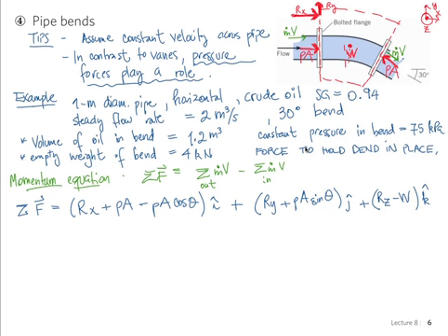Would it be wrong to put the second pressure force inside, along the momentum? Inside, like inside the control volume? Remember, we don't care about anything that happens inside the control volume. The inside of the control volume is a black box. That's the whole purpose of this type of analysis. We draw a black box. Everything that happens inside is some sort of average that we don't care about. But we're looking at the control volume from outside and want to find out how the control volume interacts with the world.